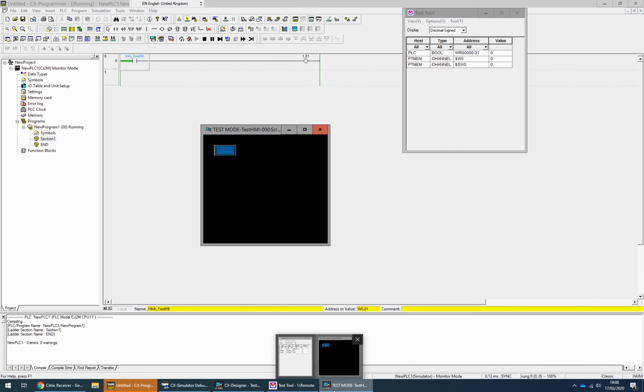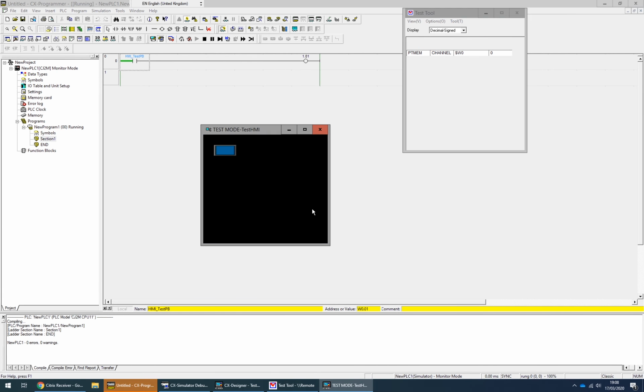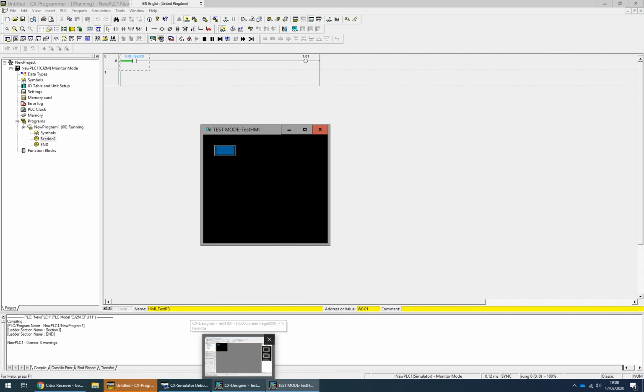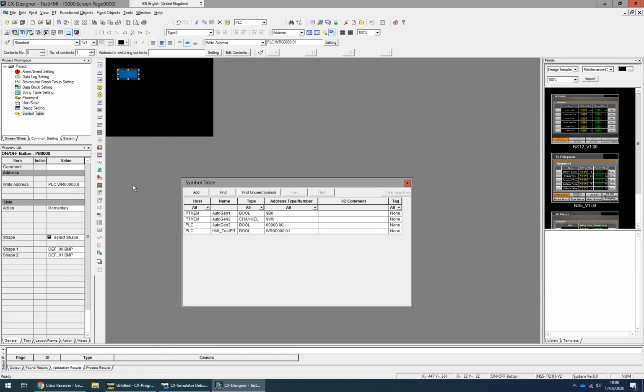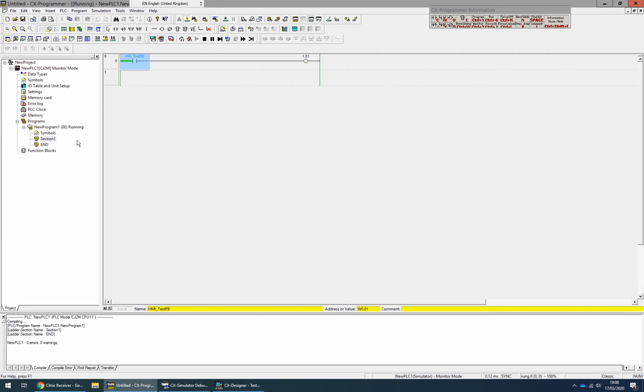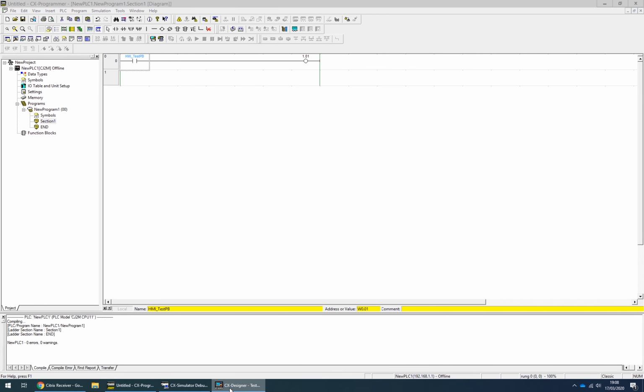So to end this, we come along and we just close this. We say yes, we want to close the test session. And now CX Designer is available again, but CX Programmer will remain online, so you need to go to work online simulator, which will take it back offline. So that's the end of the first tutorial. It's a very short tutorial on how you can configure a simple project.